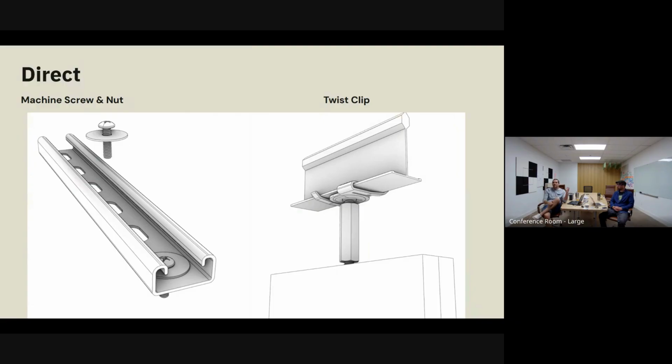Now, instead of, say you've got 12 baffles going across here, instead of having 24 cables and 24 ceiling attach points that you've got to make, you can do that in 6, right? 3 per unistrut. And then it's just a 1/4-20 machine screw and a washer, and they just screw it right into the baffle. And it's a direct mount. That also keeps it from sliding, shifting, and it makes sure that you're very level across your bottom. You don't have to go through a bunch of different suspension points and do your micro adjustments to make sure you have a level finished product.